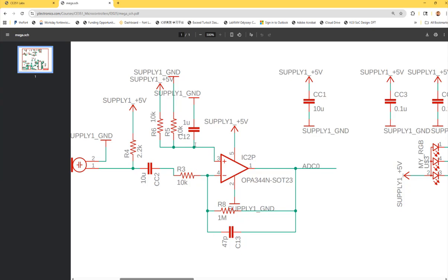So it's not getting interference between these two, AC and DC. Nor is it, if you forgot how to do it, but what I'm saying is the AC signal passes this high pass filter, gets a pure AC, and that pure AC is being superimposed onto the DC being added to the other side of the input. And that DC is what? 5 volts, right? 5 volts goes to here and then goes to 10K resistors, giving you a 50% drop. So that's actually a DC offset of how many volts?